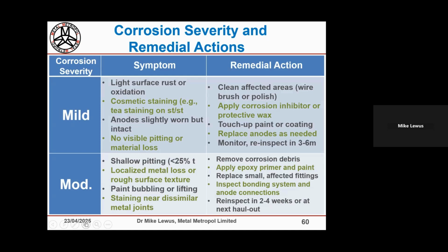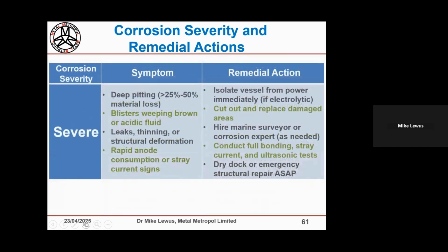I would regard paint bubbling up, particularly on the submerged parts of a vessel, as being serious, because the paint is there for good reason, to minimize corrosion and avoid compromising of subsea parts. So I'd consider that considerably serious. But it could simply be that we're talking about skin fittings and it's your bonding system that needs inspecting and closer looking at and setting up better.